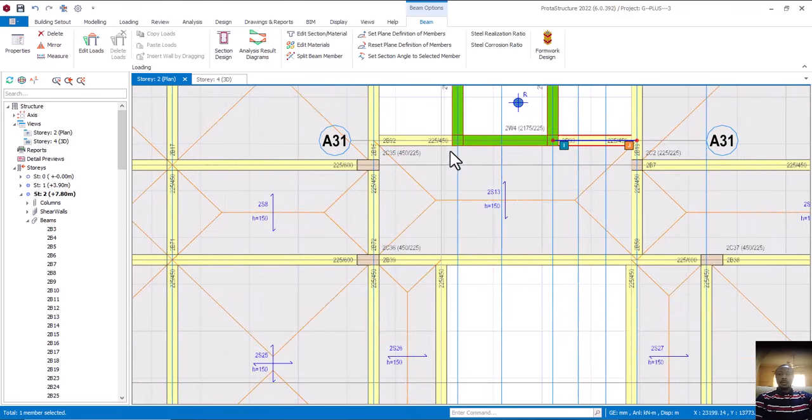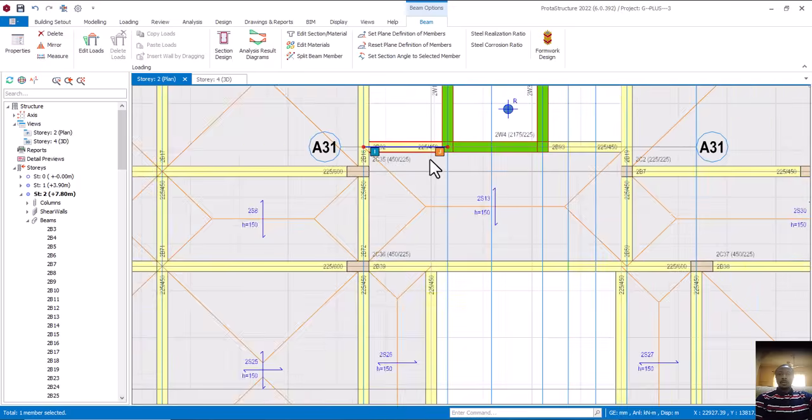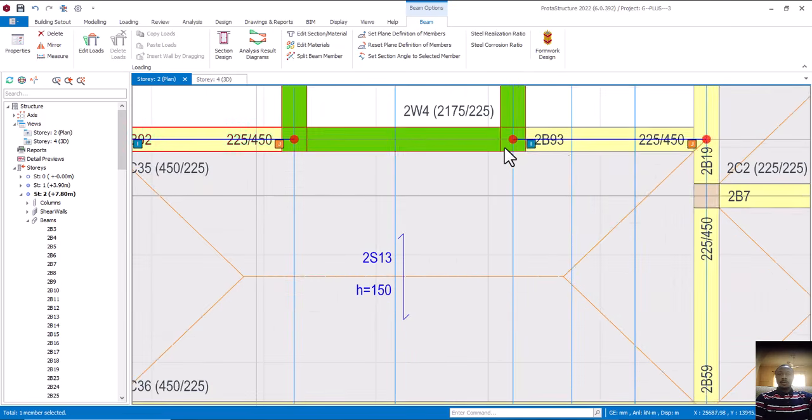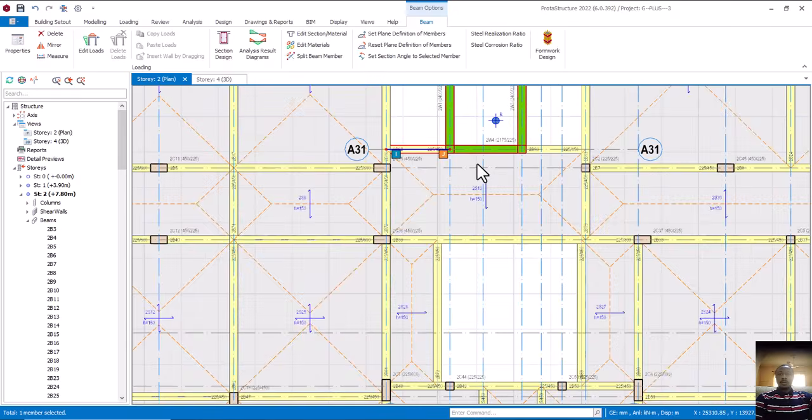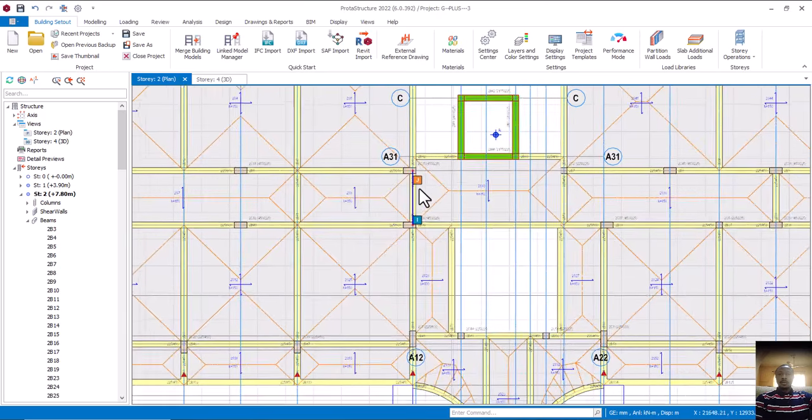We are going to hinge it. Is that okay? This one, that's at J. We are going to hinge it at J, and also hinge it at J because there's no continuation. Can you see? No continuation of this beam. It's terminated here. It's seen as well as the beam end condition. Is that okay? So that is that.